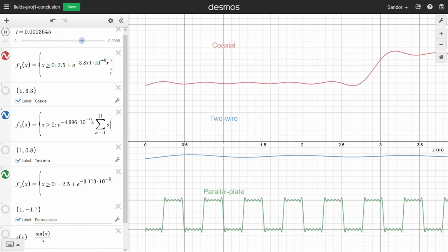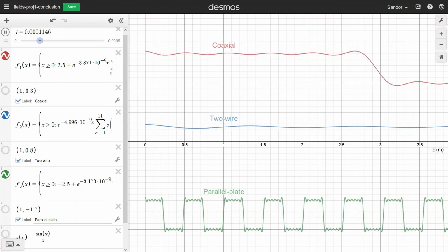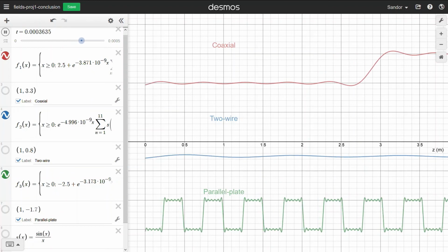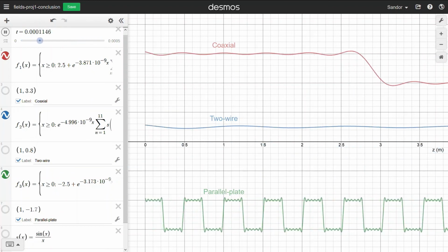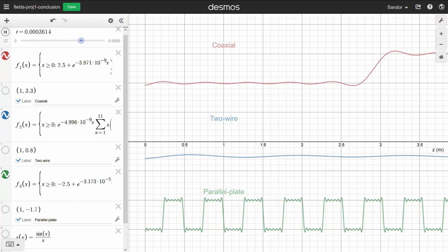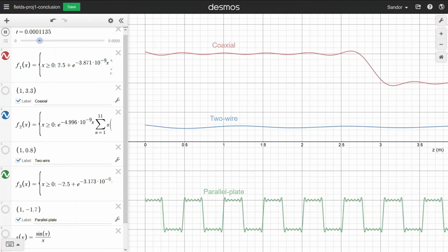So, in these videos, we visualized the relationships between the T-line parameters and wave propagation, and saw what distortion looks like on a real line. We then introduced the Heaviside condition for eliminating distortion and saw the effects. In conclusion, the Heaviside condition does reduce distortion, but the skin effect sabotages this at higher frequencies, a problem that needs to be solved another way.